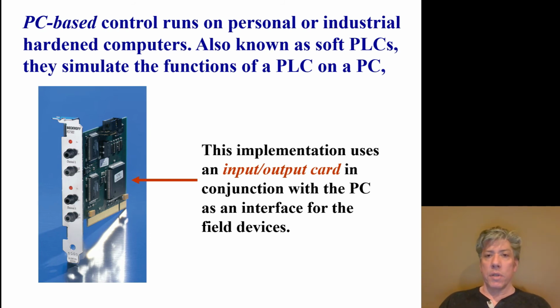Now, if you're using distributed I/O and you can connect a bunch of remote I/O modules to the PC, then it's not so bad, because the PC can be set into an air-conditioned office or something and operate the process over a network, for example. But there again, PLCs are made to be extremely reliable, not only against dust and dirt, and obviously you don't want to pour water into them or something, but also against electrical noise and so on.